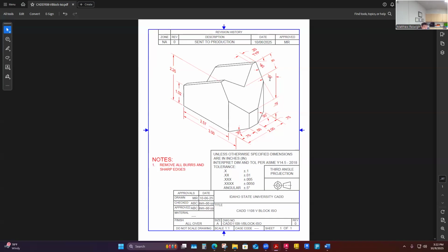I'm just going to say, well, I've got like a 30 degree. Seems like this is 30 degrees from this point, like sloped back. This one, I don't know what it is, but it's like 90 from kind of this surface here to there. So I've got some weird angular measurements to work from. They don't help me define linear lengths necessarily. And if I was in the front view here, with my eyeballs on this surface, perpendicular to the surface, I'm going to see this true length. This is going to look just like how long it actually is in my front view.